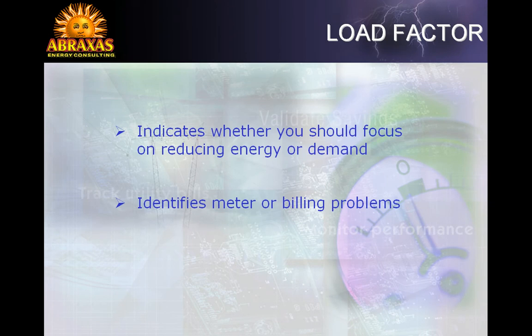How can load factor analysis help you as an energy manager? Once you have identified which buildings you want to make more efficient, you can use load factor analysis to concentrate your energy management focus towards reducing energy or reducing demand. Load factor analysis can also be used to identify meter or billing problems and identify which buildings are leaving their equipment on during off hours.